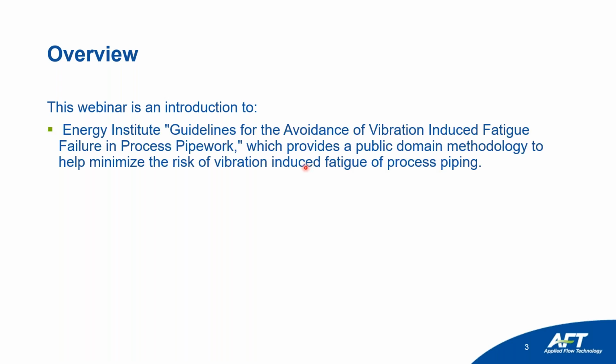So today we'll have an introduction to the Energy Institute guidelines for the avoidance of vibration-induced fatigue failure in process piping, which provides a public domain methodology to help minimize the risk of vibration-induced fatigue for process piping. This is a guideline that has gained a lot of popularity in European and Asian countries, not so much in the US. And we have seen it in congresses that we have attended both in Asia and Europe.